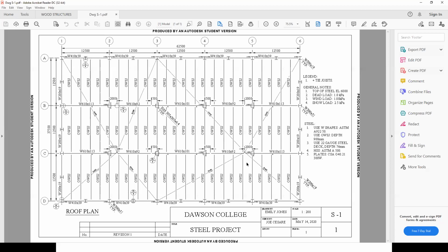So as a matter of fact, if I'm not mistaken, if the top is steel here, there's a slight mistake here, because if the joists are sitting on top of the beam, there should have been minus 500 and then less another 125. So this was a mistake, and I probably picked up on it and I marked it wrong. Okay, so keep that in mind, because the 2% is, for example, what I'm trying to say is that 6,000 is where your steel is.